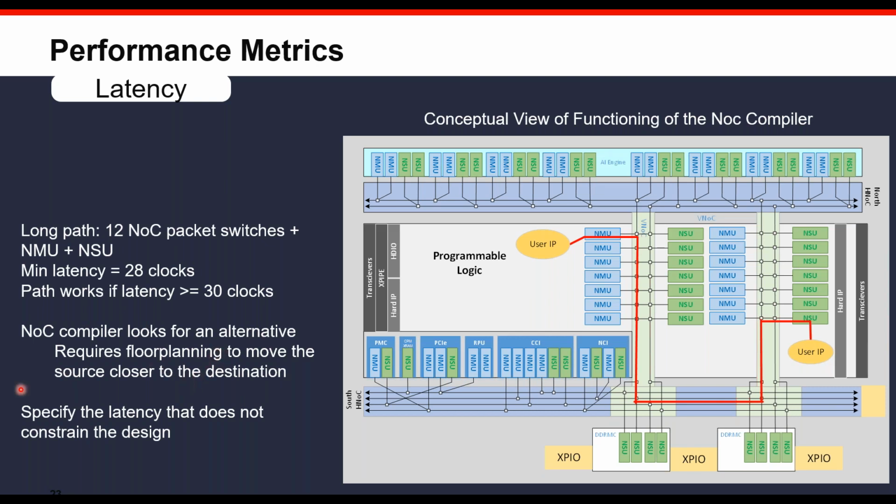More than anything else, you want to make sure that you're specifying a latency that doesn't over-constrain the design or become your first order issue, such that the tools spend all this time and just can't get here from here. Make sure that things make sense. It's precise and pristine when you deliver your design constraints. Make sure you're doing the same thing with the latencies as you work your way through.